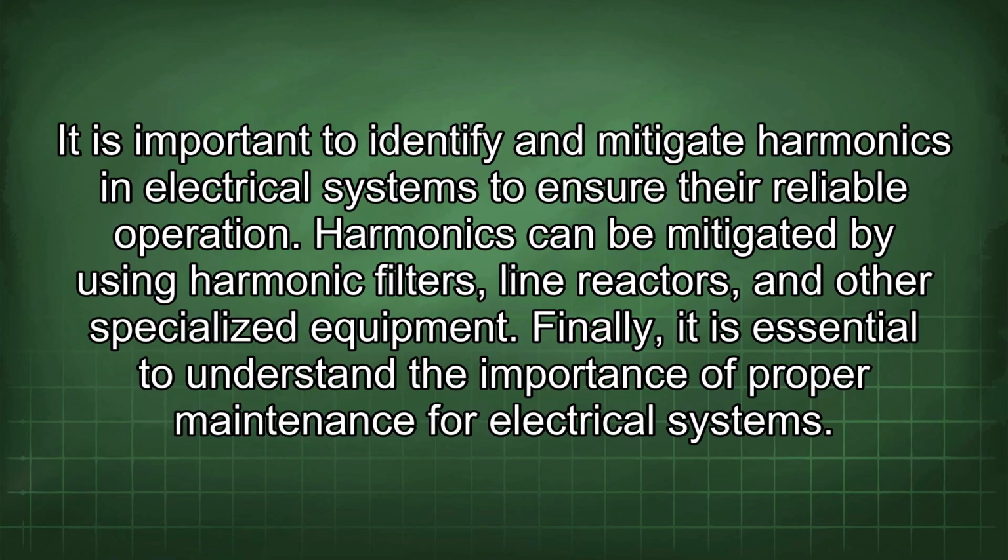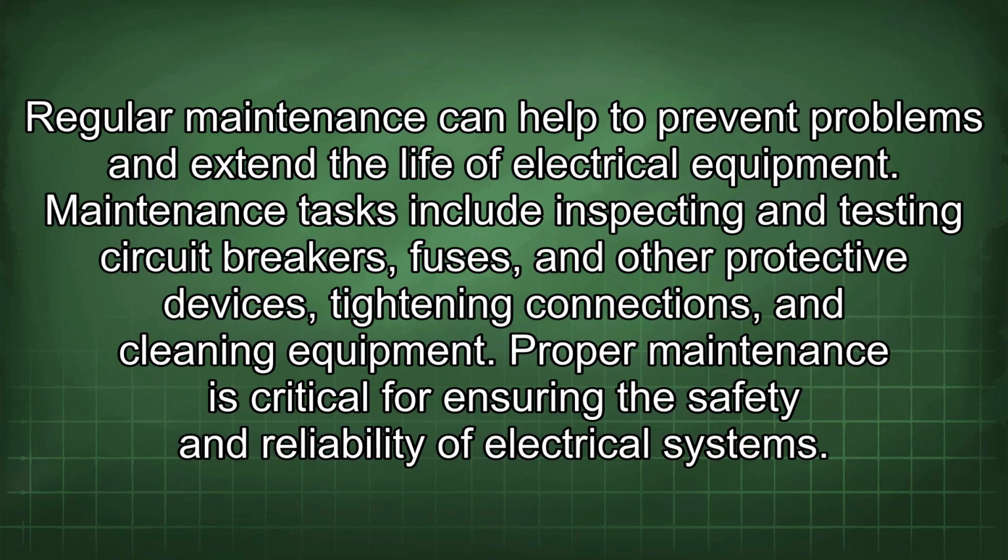Finally, it is essential to understand the importance of proper maintenance for electrical systems. Regular maintenance can help to prevent problems and extend the life of electrical equipment. Maintenance tasks include inspecting and testing circuit breakers, fuses, and other protective devices, tightening connections, and cleaning equipment. Proper maintenance is critical for ensuring the safety and reliability of electrical systems.